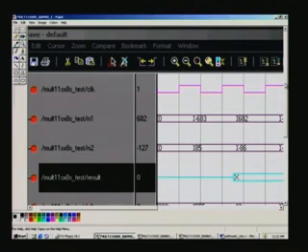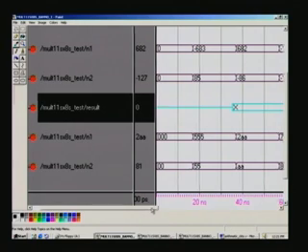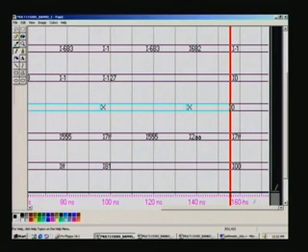So, that is what we have seen here, 0 into 0, minus 683 into 85, 682 into minus 86, and so on. This is in hexadecimal and this is in decimal, and the final result is here, and that is available only after 8 clock pulses. Each clock pulse is at 50 megahertz, 20 nanoseconds, so around 160 nanoseconds you get the result here, and that is what the result is, 0 here.